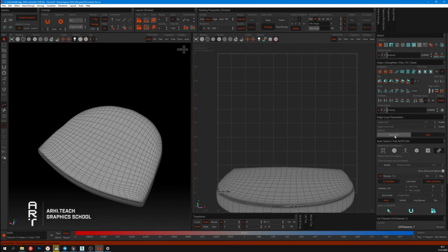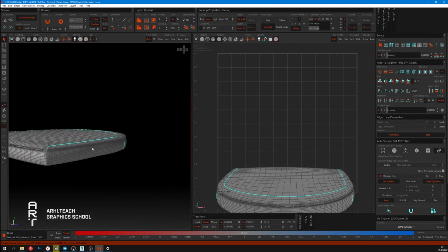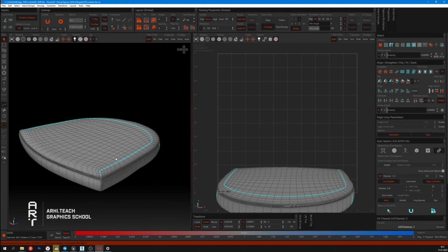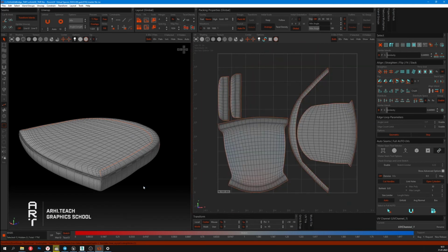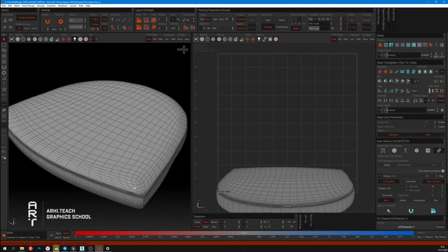There is also a geometric button. It turns on the algorithm of the automatic size analysis and edge selection. As we can see, the program has chosen edges in an interesting way. Let's see how it looks on the unwrap. Press Cut C, press Unwrap U key. So the program did quite well. In some cases it might be helpful. There is also a stop button that allows us to restrict the algorithm of automatic edge selection with those edges that have already been selected.